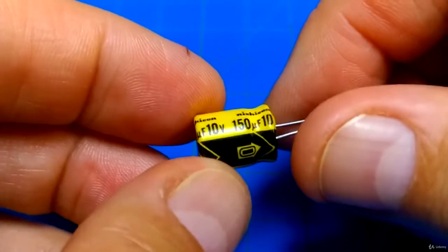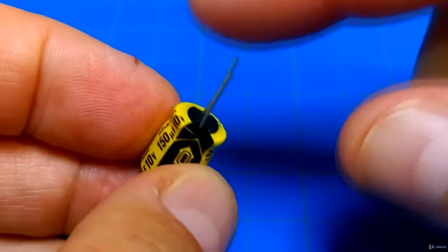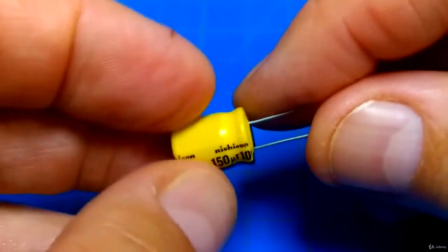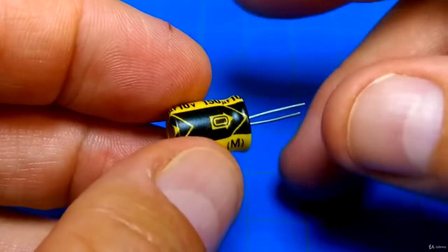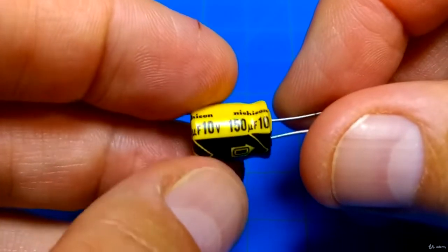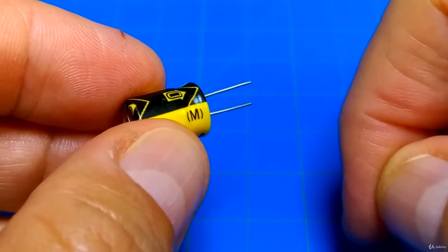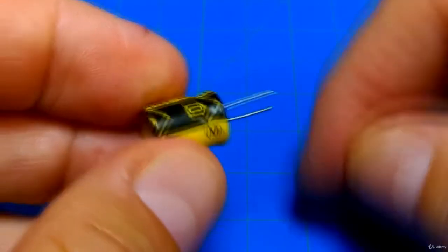And so a couple things. First, you see this electrolytic means it's polarized. So it has a plus and a minus, and it works in that direction. If you don't put it in that direction in your circuit, it'll explode or not function or do bad things. All right, next, it has this negative here. That means this is the negative side, and the other side must be the positive side.